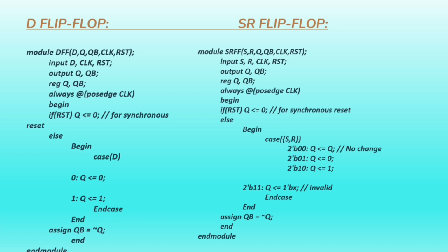Now let us understand what is SR flip-flop. This is the most common flip-flop among all. This simple flip-flop circuit has a set input S and a reset input R. In this system, when you set S as active, the output Q would be high and Q bar would be low once the outputs are established. The state of the circuit is maintained until S or R go high or power is turned off.